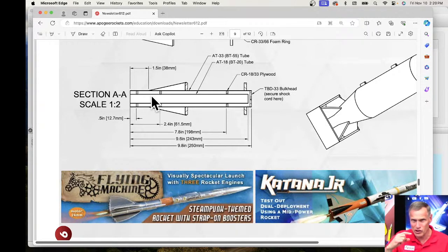The heat propagation, particularly with paper motors like an Estes motor, heat propagation through the paper. Paper is an insulator. So the heat takes a long time to soak its way through the paper to get to the outside of the motor casing. So you're probably okay. Now where it gets really hot is reload motors, which are in an aluminum case. Aluminum is not an insulator. Aluminum transfers heat like nothing. So those get really hot really fast.